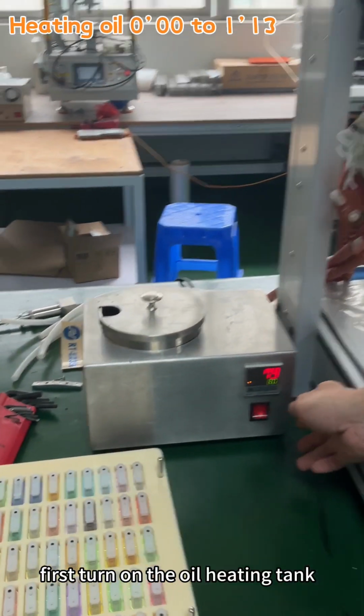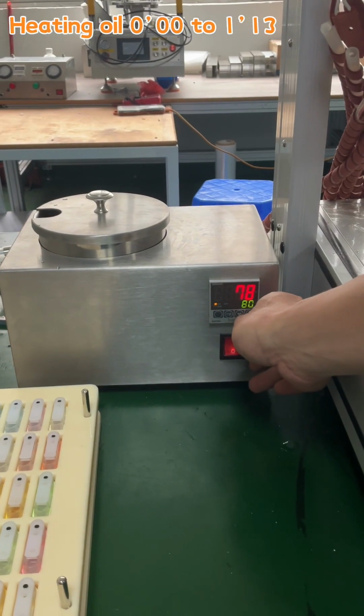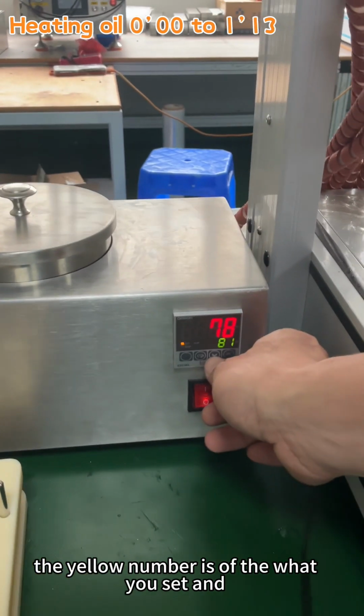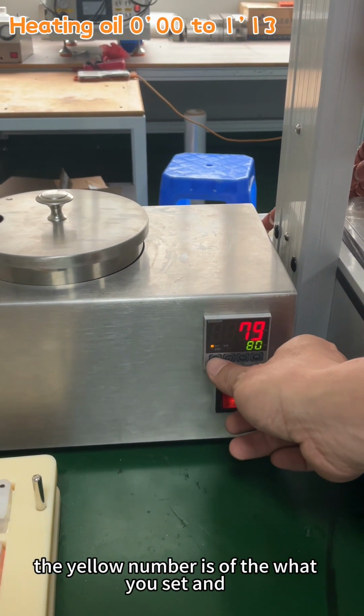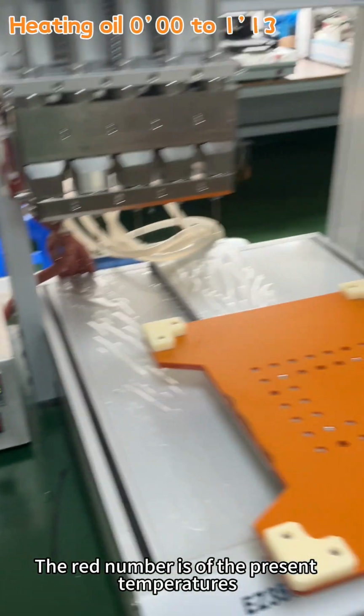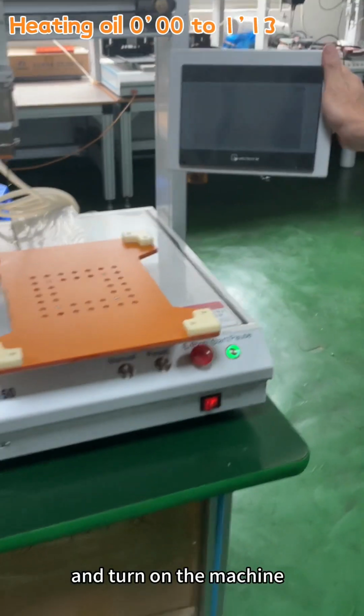First, turn on the oil heating tank and set the heating temperatures. The yellow number is what you set, and the red number is the present temperature. And turn on the machine.